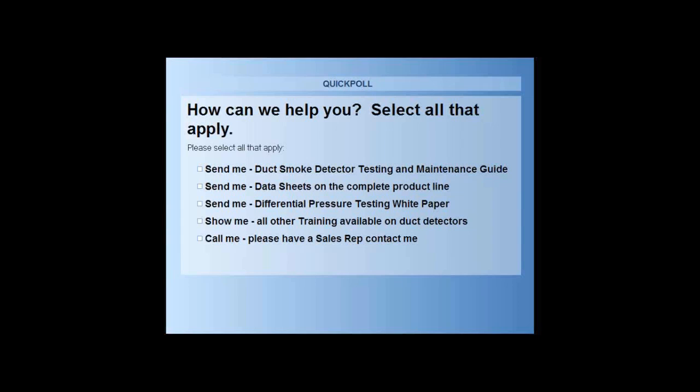So Lisa, which detectors need a coil and a power supply for remote testing? You could potentially need that in two situations. Our 2-wire duct smoke detectors need a coil all the time for remote testing. Also, our intelligent duct smoke detectors can be used with either a standard open area intelligent smoke detector head or what we call a remote test capable head.